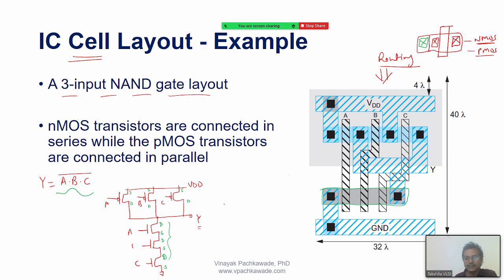So what I'm doing is that 3 in series means instead of taking 3 individual transistors like this, 1 and then again 2 and again 3, I can draw one single transistor, right? So total L of this transistor will be 3 times L, right? Let's say TL, that is the total length of this transistor. So that's how the series connection is made.